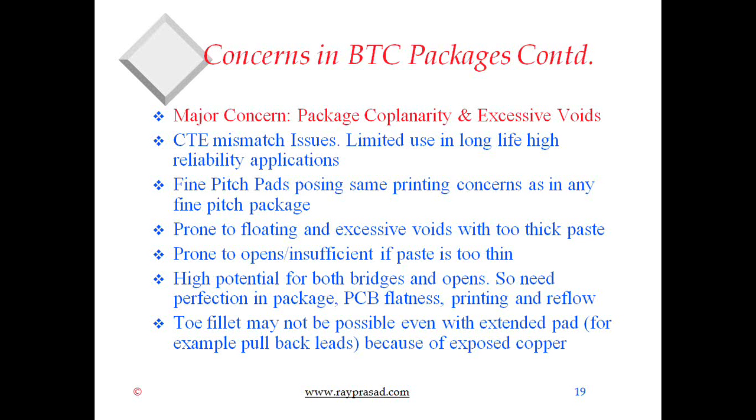So if you have a long shelf life, long life application, you've got some concern there. And if the pitches of these BTCs are very fine, you might run into printing issues. If you have too much paste, it will start floating and cause a lot of voids. And if you have too little, then you get opens and insufficient solder.